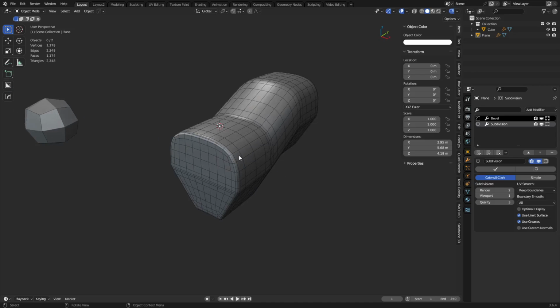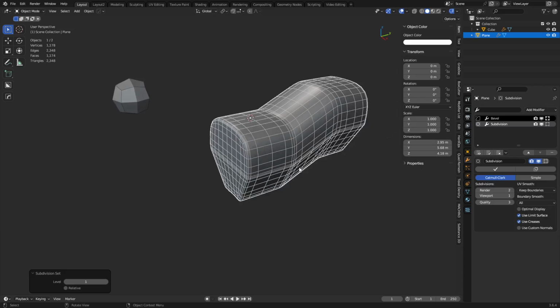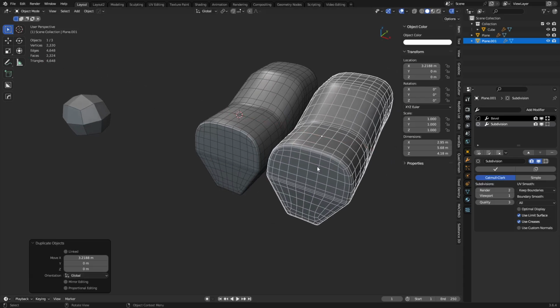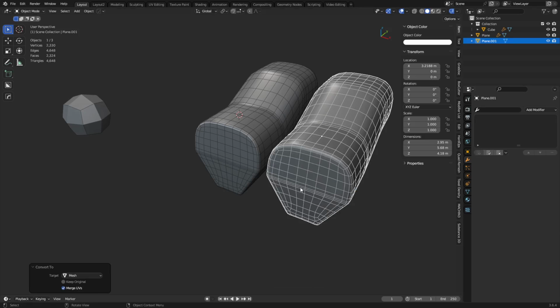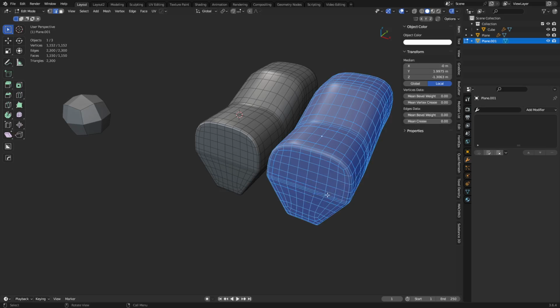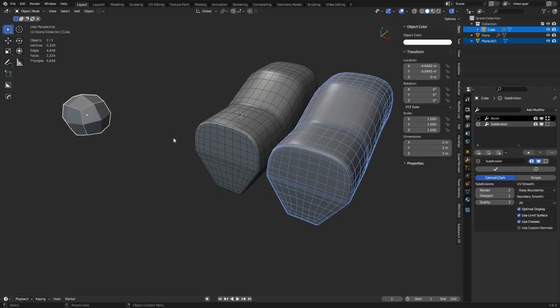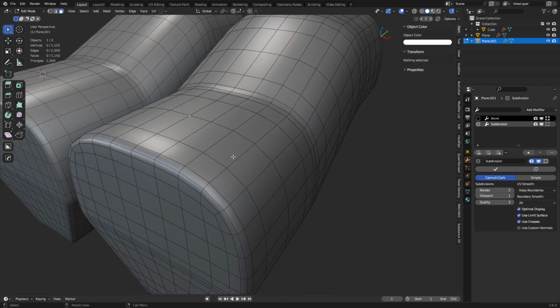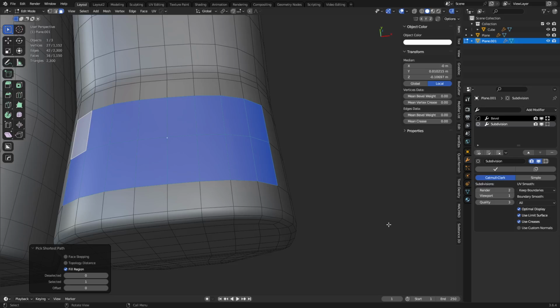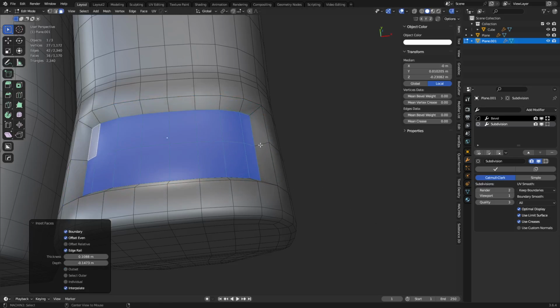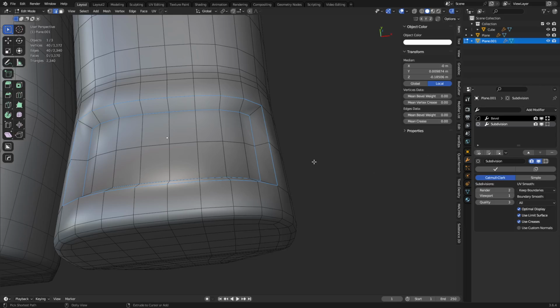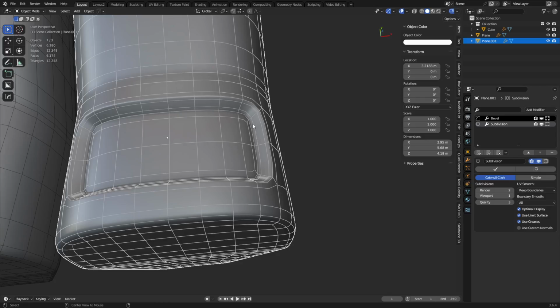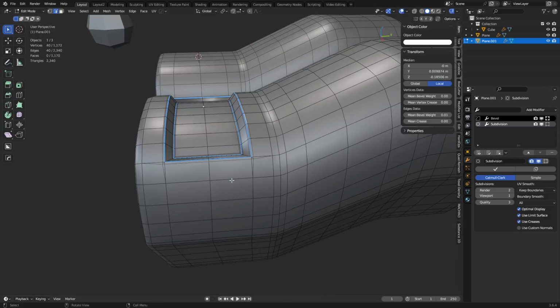And at a certain point, you'll take your model and you'll say, yeah, I want to collapse it later. So it's very easy to work with this now in iterations because all you do is make sure your level one subdivision bevels are on, convert it to a mesh, go into edit mode, remove all your bevel weights, okay, and then take this, shift select that, Control L, copy modifiers, and so you have the same setup again, and you can go through this further. And whenever you want to make your changes, you can do an inset, hold control, loop select this, boundary select it, and then Control Shift E. You could do a number like that. And so a little bit less destructive perhaps.